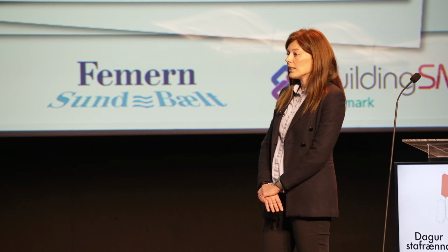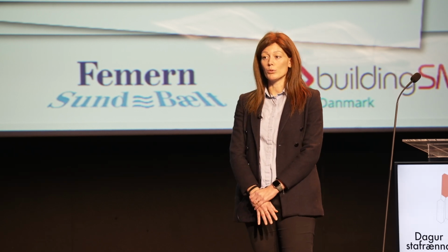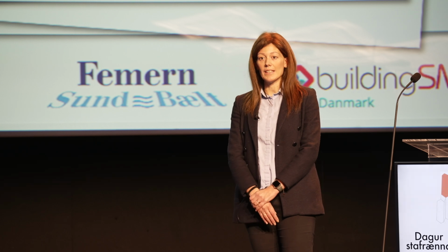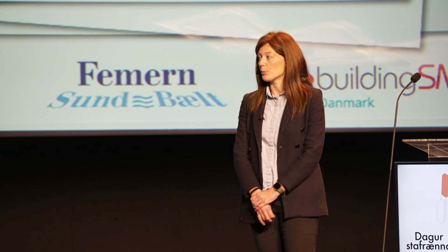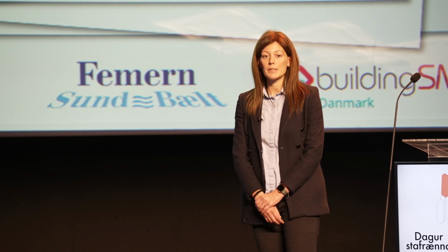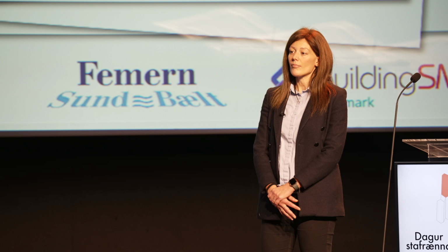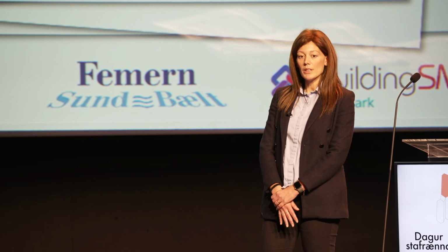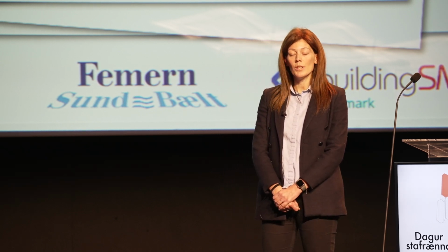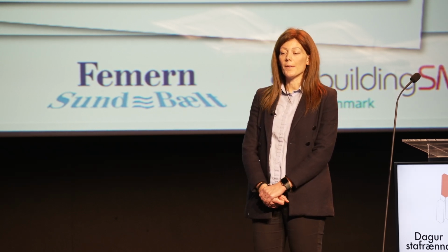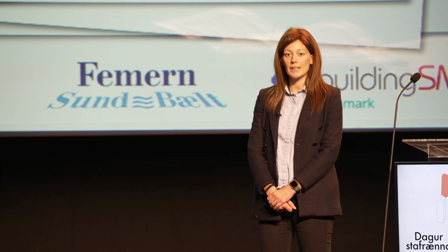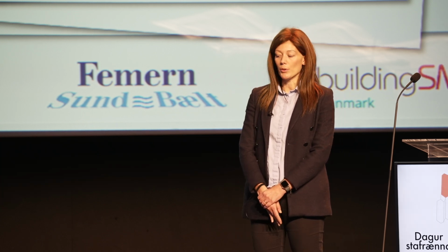Basically, what we would like to do now is to share this IDS and the reports that we got from Building Smart Denmark and Building Smart International with our contractor, to make them aware of the issues that we are facing and the current status of the models and the properties within the models, but also to give them the IDS tool so that they can check the quality of the model beforehand, before submitting it to us.